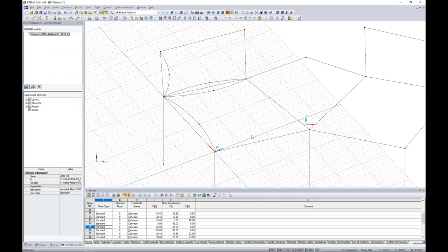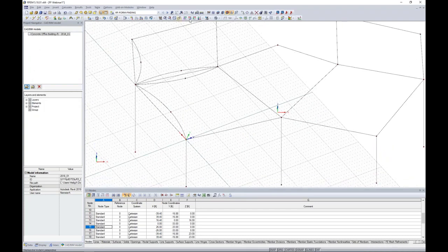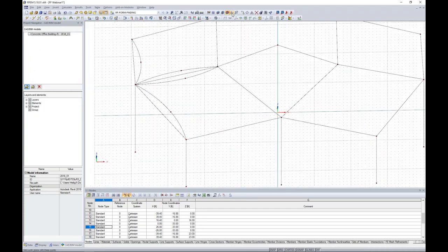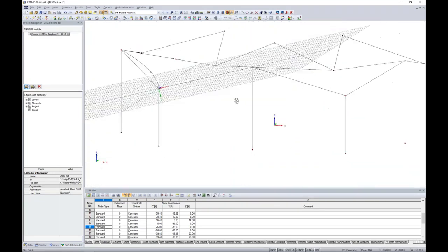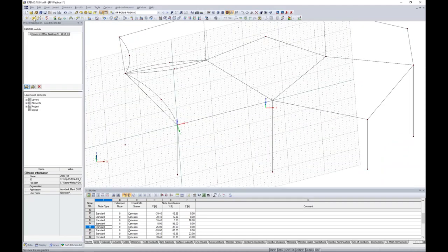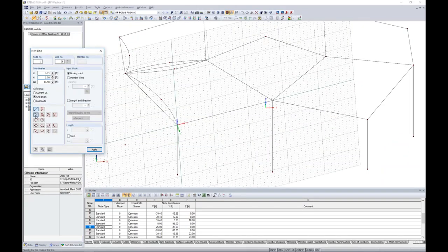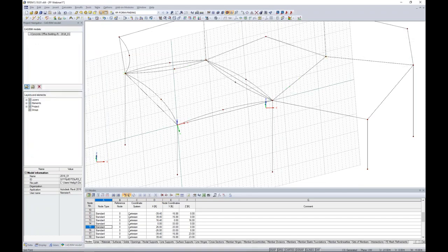We need to lastly do so over here. So we click this option up in our toolbar for a user-defined grid, click our 3 new points, and now we have the specified angle is given. We go back to draw a new line element as an arc with 3 lines and continue on with this process for our additional cable elements. And one more time for our 3rd cell.